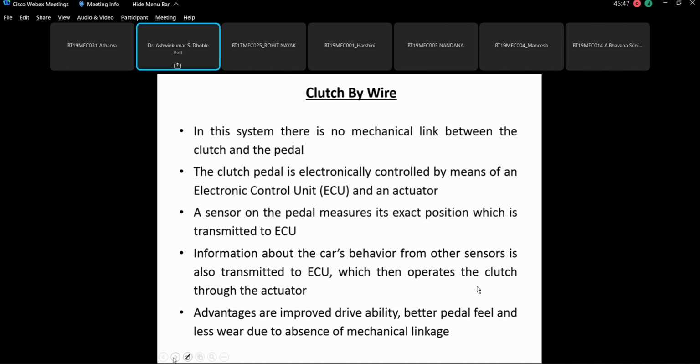And the problem with the sensors is your sophistication level is very high, but the moment if the sensor parameters drifted away from the original one due to some reason, because of the temperature or because of the excessive torque which is applied for fitment of that, then there is no repair available for the sensors. You have to replace the sensor by the equivalent sensor, and for that, the roadside mechanic cannot repair the vehicle. You have to put that vehicle into service station.